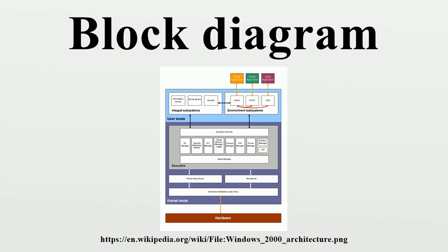An example of this is the function block diagram, one of 5 programming languages defined in Part 3 of the IEC 61131 standard that is highly formalized, with strict rules for how diagrams are to be built. Directed lines are used to connect input variables to block inputs, and block outputs to output variables in inputs of other blocks.